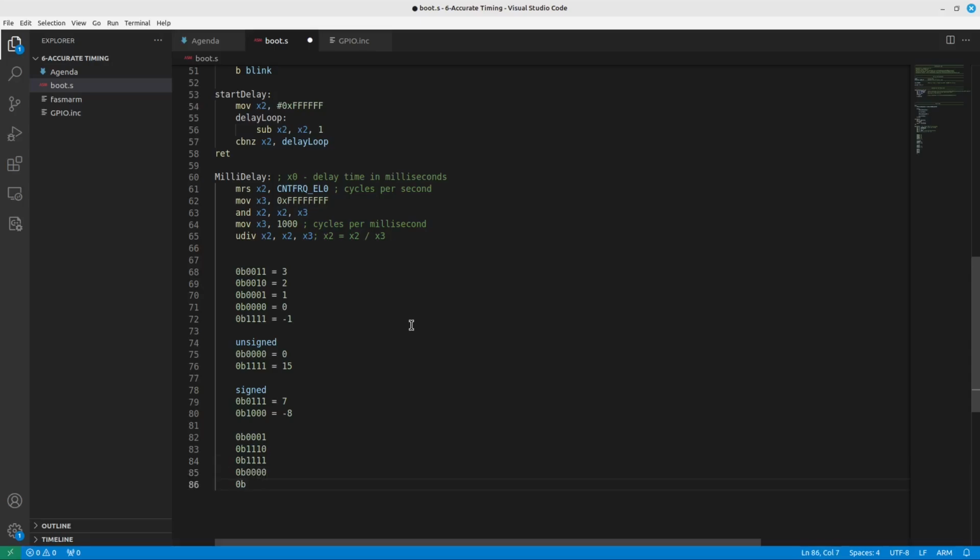And then we add 1. And we've just converted +1 to -1 to +1. Very clever system, whoever figured it out. Very smart, but anyway, that's the difference between signed and unsigned. The range stays the same. This is still a range of 15, but our positive maximum value is reduced because we are using the most significant bit to describe negative values as well. I think that's good enough for explaining signed and unsigned.